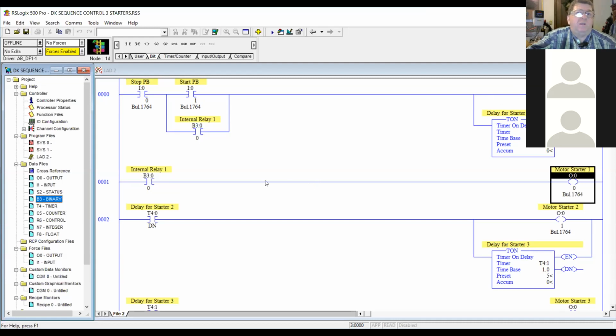Okay. I'll get with him tomorrow. Yeah, he could show you, and he could actually do a screen share with us and let us see a real routine, a real program, and we can explain to you how it works using the B3 bits in there that are internal. Just know that you've got internal relays in the PLC that you can use, and it's just like using base tags with 5000. It's just internal functions that you can use that are not real world inputs or outputs.